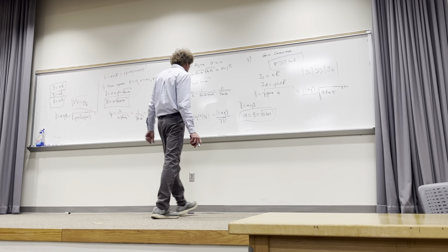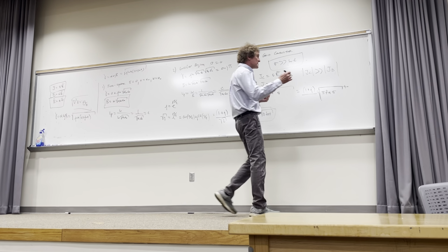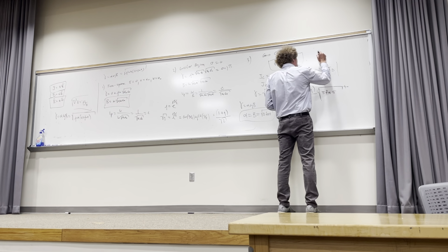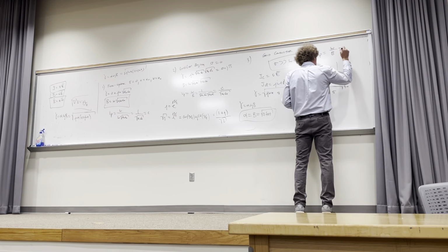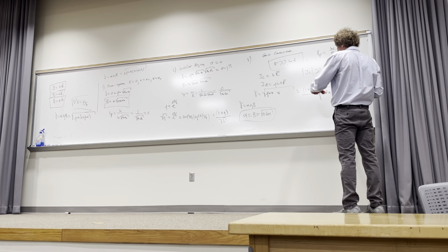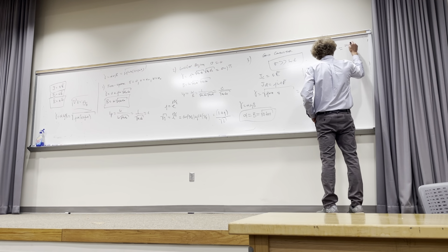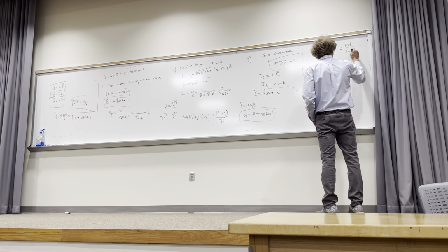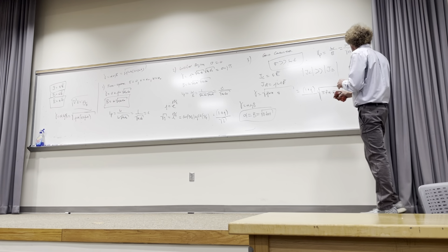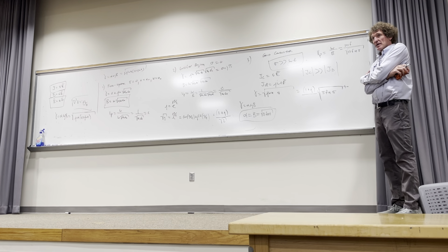Now, take a look at the velocity for a good conductor. Velocity is still the same. Phase velocity in a good conductor is omega divided by beta. And I can have it with this and that, doesn't matter. So omega is 2 pi f over that, which is square root of pi f mu sigma. That's phase velocity in a good conductor, right?